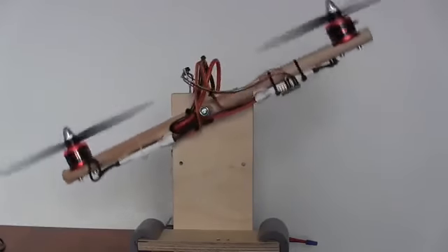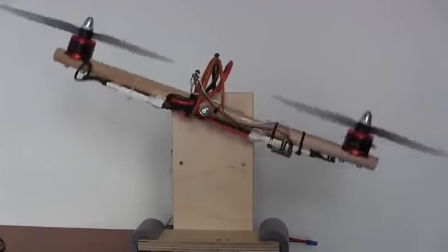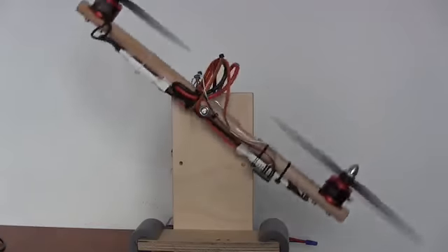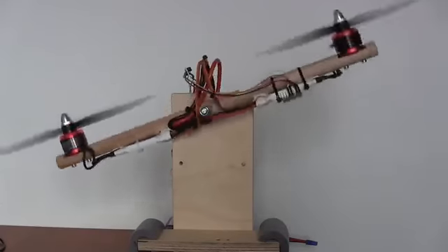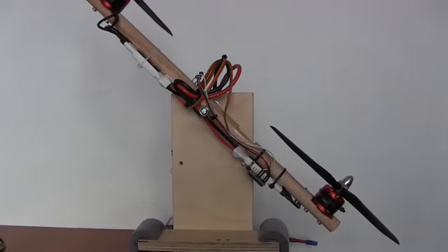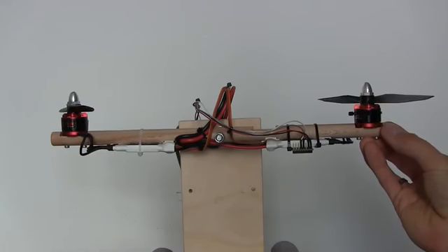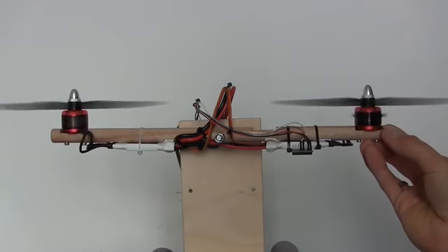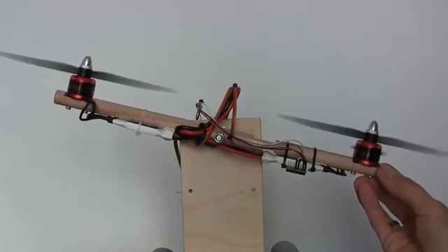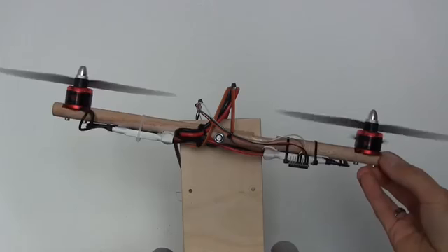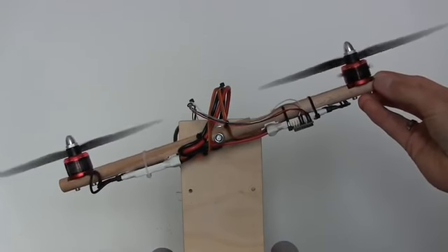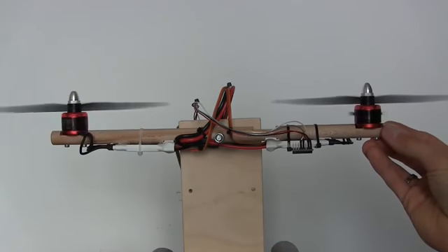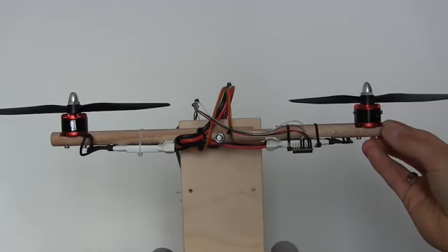Now when I show only the I controller on the test stand, you can see that it overcompensates just like the P controller. Only the oscillation is much slower because the output slowly increases. But it keeps overcompensating. When I keep it level at the start, there is no controller output. But when I pull it down, it starts to fight me until it is back in the same position as it was before. This is because the controller output only changes when there is angular motion. When there is no angular motion, the controller output stays the same.